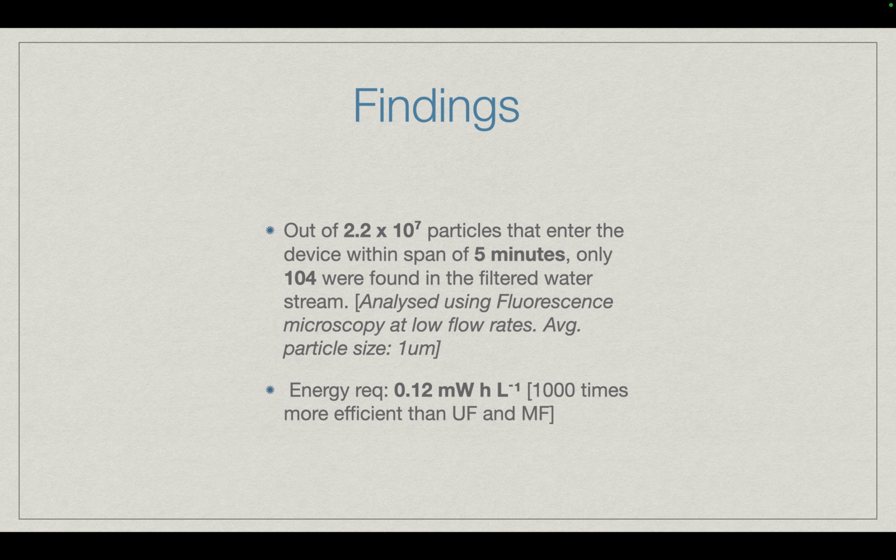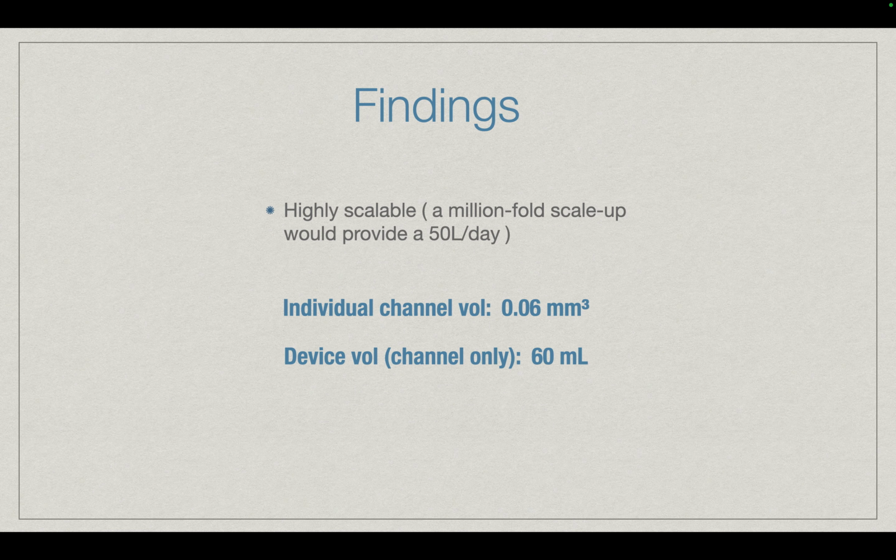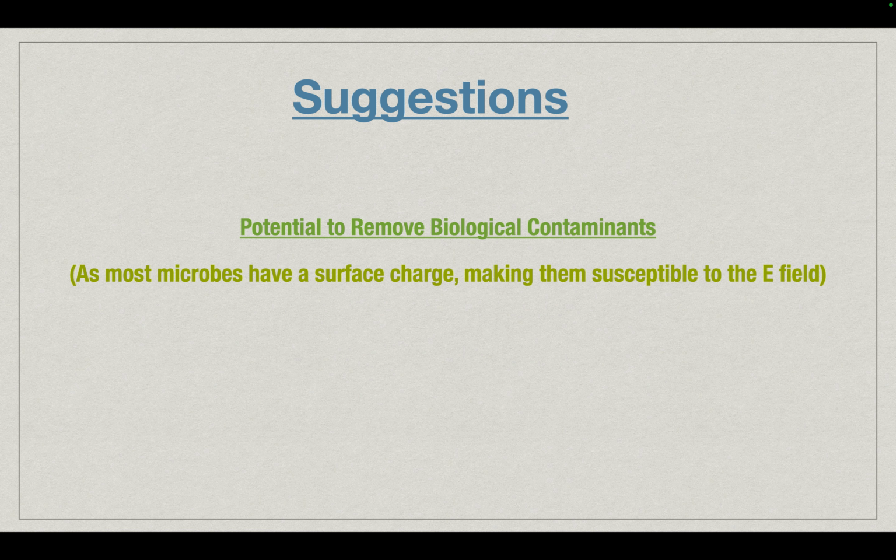The energy required is also very, very low, almost 1,000 times more efficient than ultrafiltration and microfiltration. The process is highly scalable, of course, because all you need to do is keep stacking these channels. And also this has the potential to remove biological contaminants, because microbes also carry surface charge, so they will also interact with that and move away in that microfluidic channel along with the suspension particles.